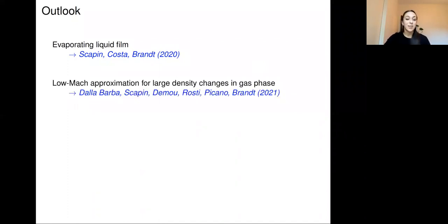Even further on, this code has been extended again. I can hardly keep up with them. Another extension with a low Mach approximation. So this allows one to simulate large density changes in the gas phase without worrying about acoustics. That's what the low Mach approximation permits.